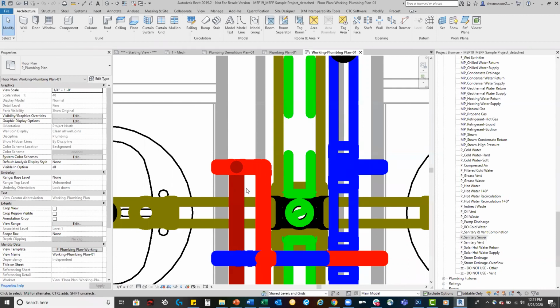Now, if the question is more about what units are available to you maybe in Revit, Revit only sees GPM and fixture units as units of measure for flow through pipe, okay? Now you can get to things like cubic feet per hour with a little bit of math and GPM trickery, right? It's another thing that the MEPPP has done is that they're propagating two things that Revit natively doesn't do. They're propagating CFH for gas piping, and they're propagating square footage for rainwater leader calculations, which is actually pretty nice. You can click on your rainwater leader at any point and know exactly how much square footage it's responsible for. So I hope that answers your question.